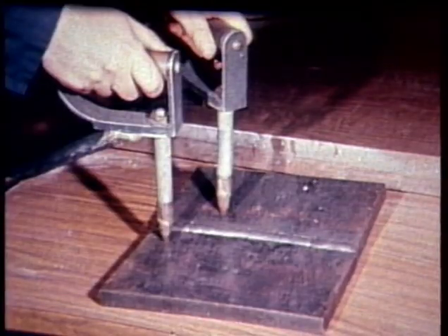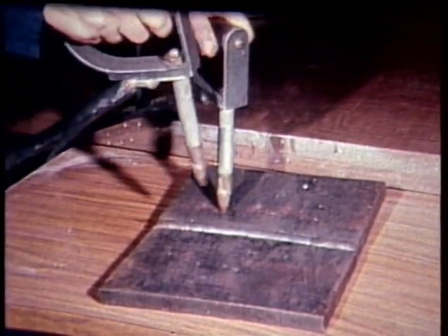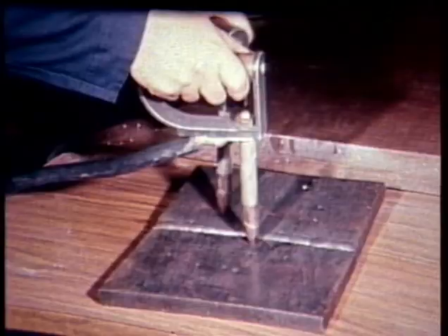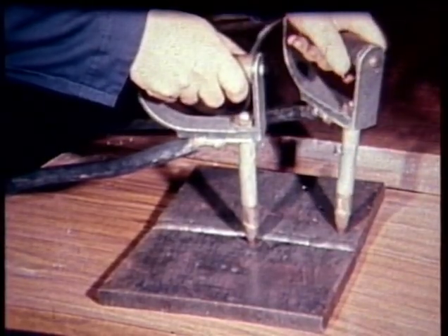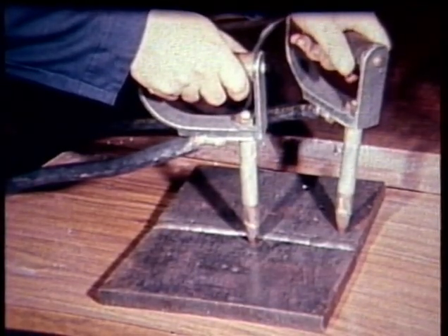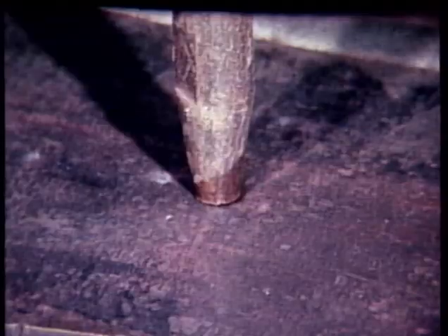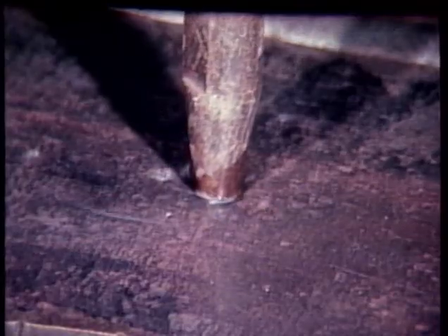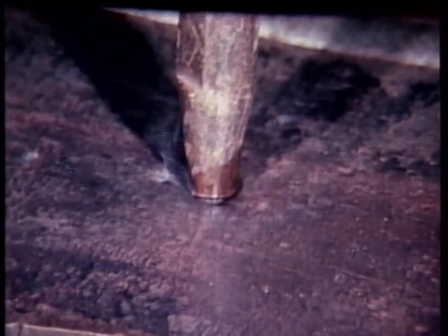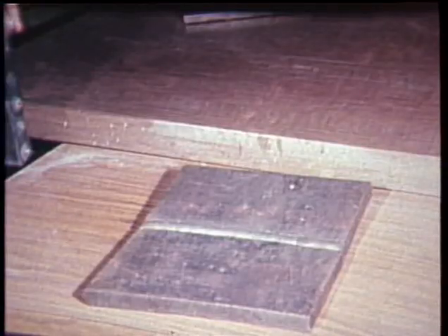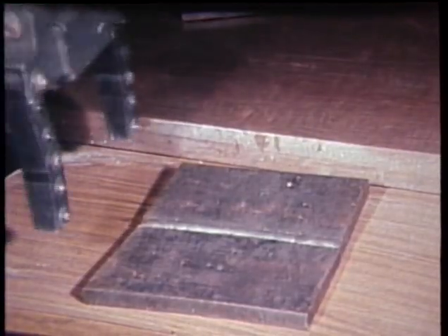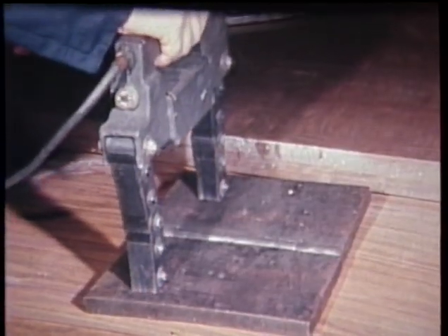The prod method is often used to create circular magnetization by walking the prods along the weld to provide full coverage of inspection. Extreme care should be taken that no electric arcing takes place between the prods and the part, as this can damage the surface. Longitudinal magnetization can be applied by a coil, wrapped coil, or yoke.